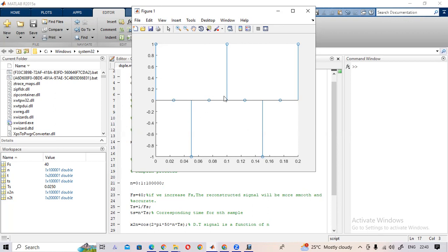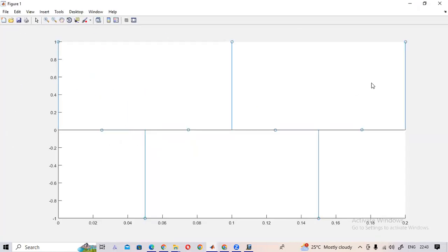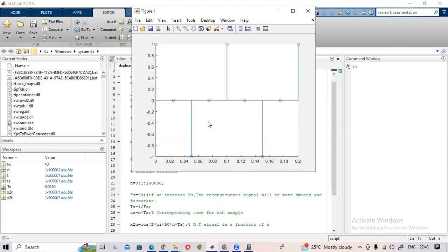What is the period of this signal? This is a discrete time signal, so we sample this. What is the period of this signal? Please answer quickly. How do you evaluate it? You need to select two consecutive points and count the number of samples. That's enough. Very easy.